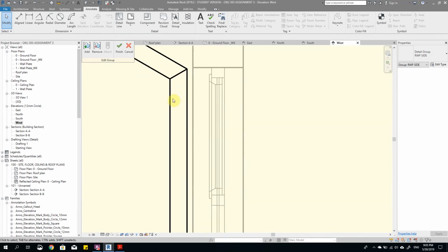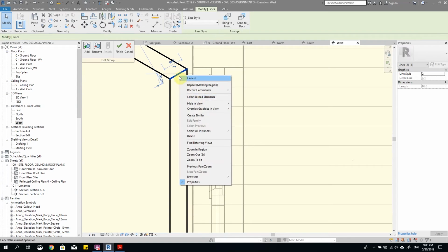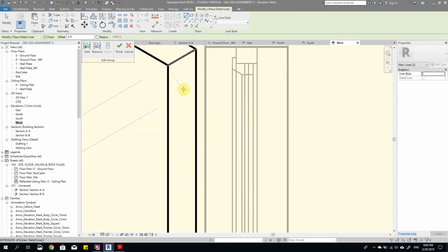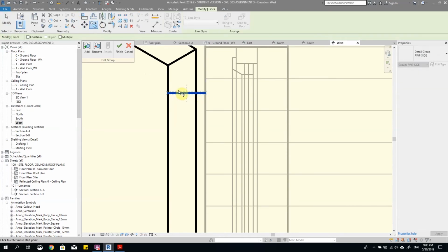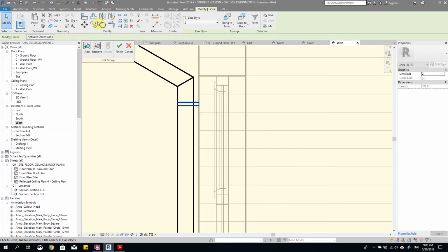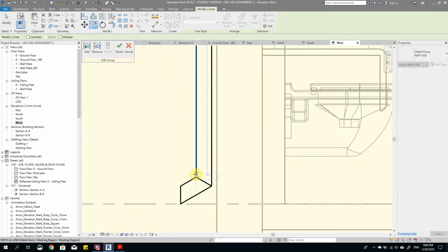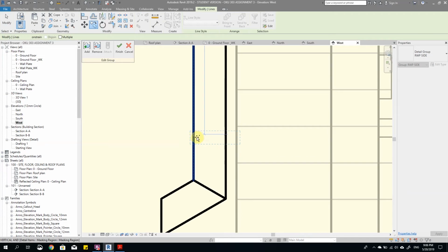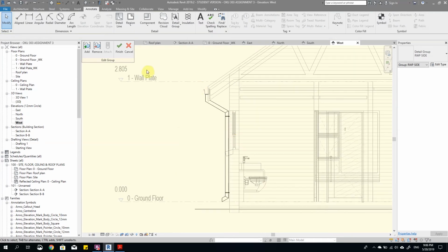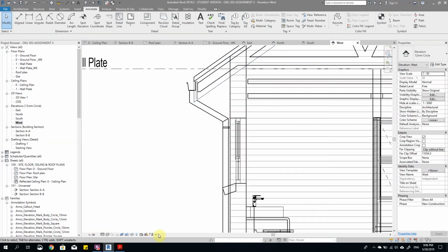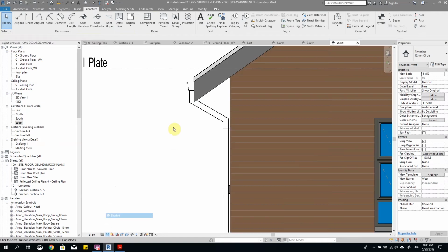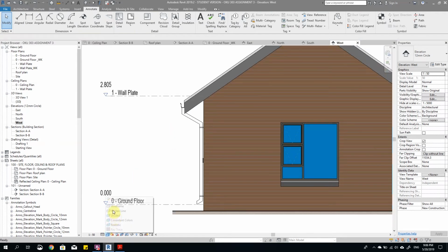Another thing I need to show is just some support. So right click, create some detail lines. So create similar, line weight 2, grab one in the middle, take this back, copy this guy down 15 mil. Okay, grab this line work, and you're going to copy this guy, copy, and we're going to put it in the middle of this. Okay, so it's about over there. Excellent. So there's our gutter in place. Okay, if I switch off my hidden command, shaded, my apologies, hidden.